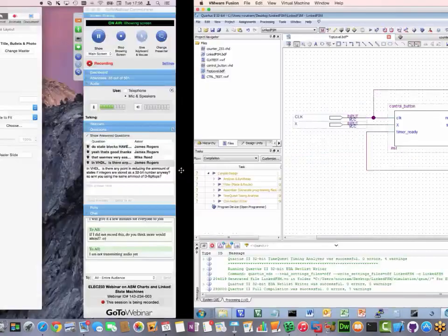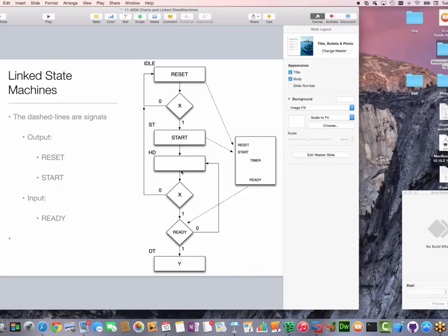And I'd like you to, well, it's up to Phil, but as the module leader, and I'm involved with the assessment of Phil's coursework, I would encourage you to try and think like that. For example, take the pulse width modulator and build it on its own and test it on its own. You can simulate it before you actually synthesize it and then signal tap. So try and do that. Try and break things down a little bit.